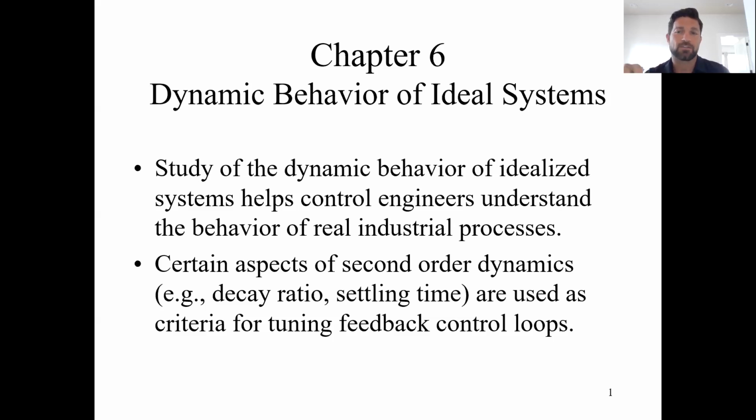So it's useful to understand the dynamics of a process. By looking at characteristics of the behavior, which can be response time, gain, and sometimes things like how much oscillation there is in a process, we can determine what the tuning parameters should be for the process.